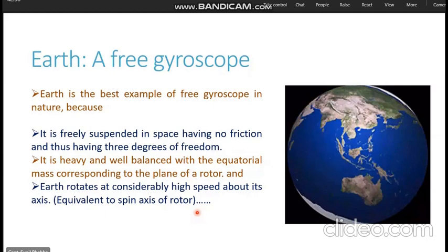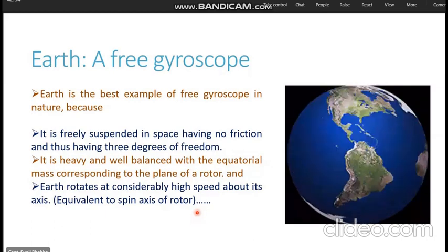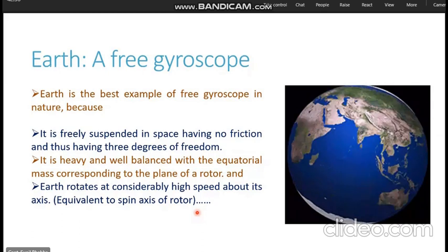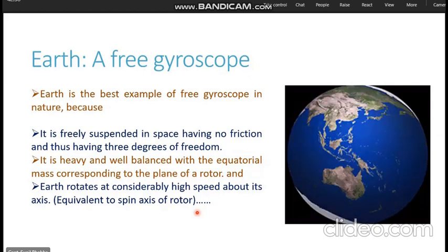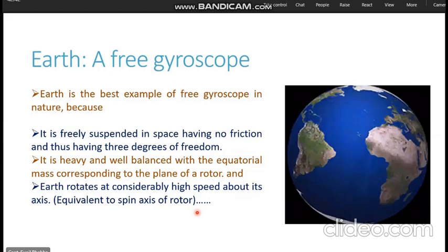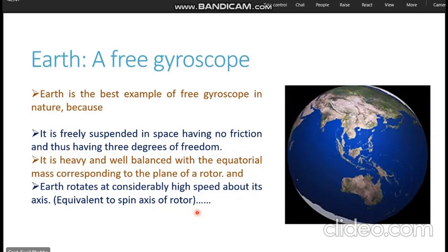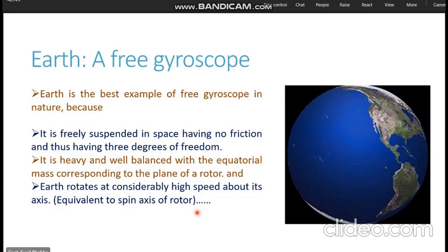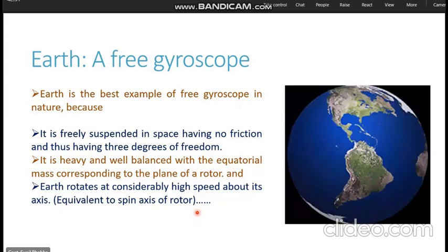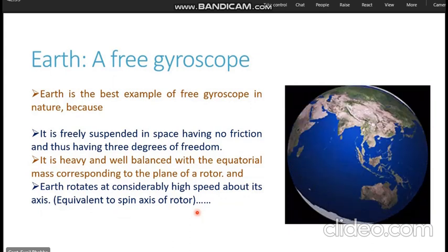As we move away from the equator and go towards the pole, the speed starts to reduce slightly, but you can calculate the speed with which the Earth is moving with the formula 900 cos latitude. So at the equator, 900 knots is the speed. At any other particular latitude, the speed can be calculated by the formula 900 cos of lat.